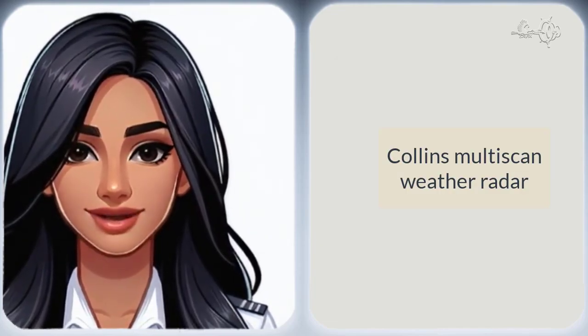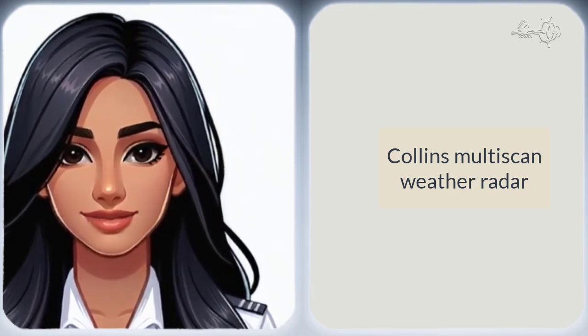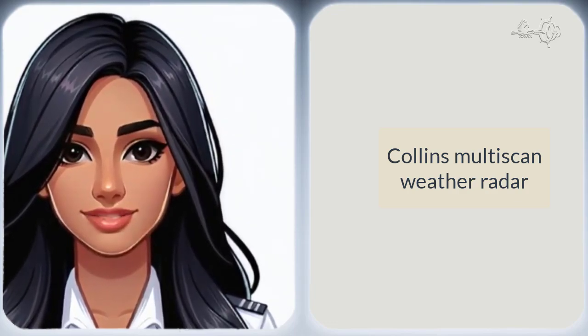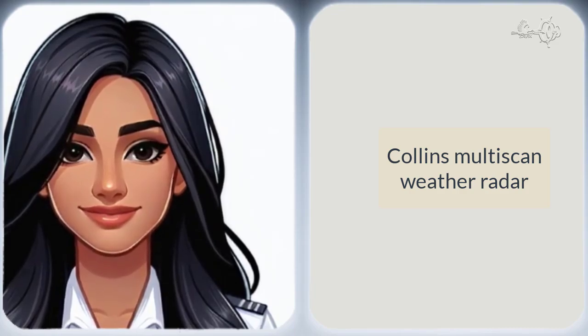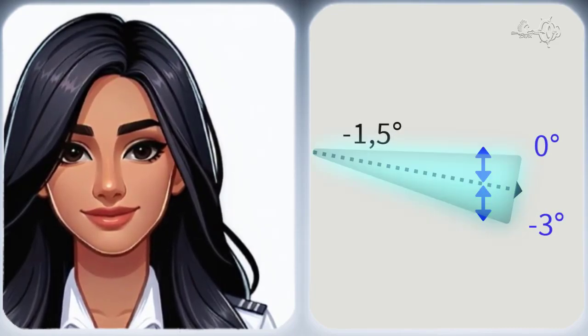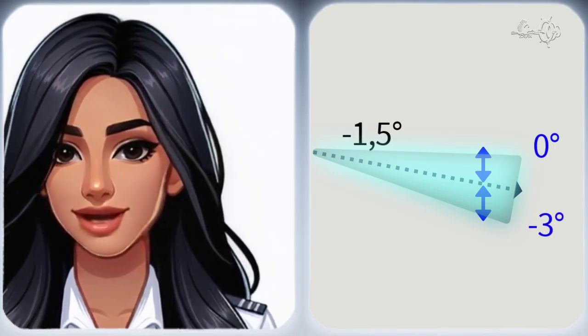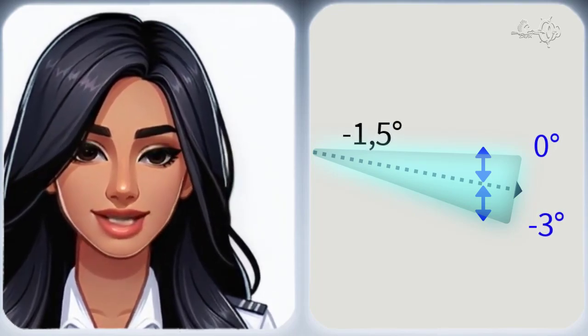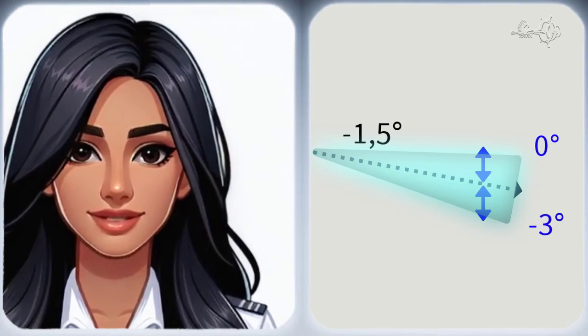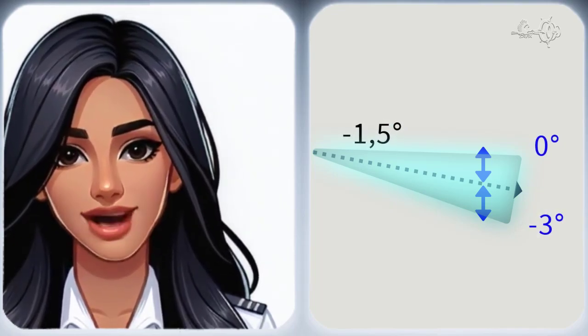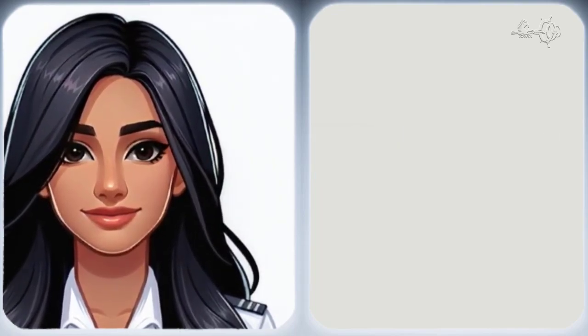Interesting to be aware as well is that the tilt angle displayed on the navigation display is the average of the lower and the main beam. Applying this further, when the pitch angle in cruise is found at, say, -15 degrees, the lower edge of the beam will be aimed around -3 degrees.